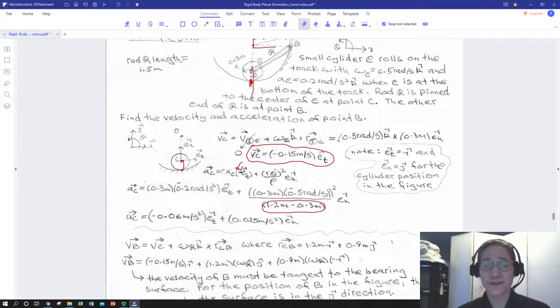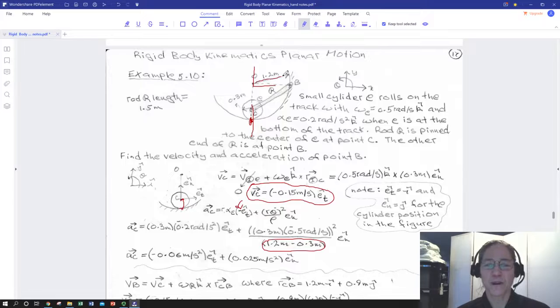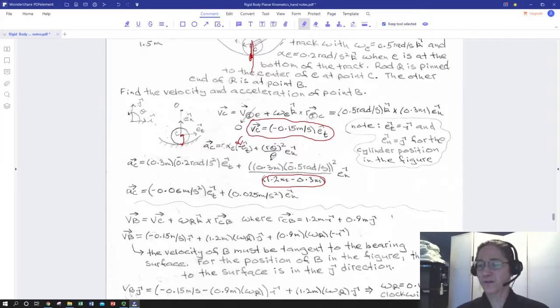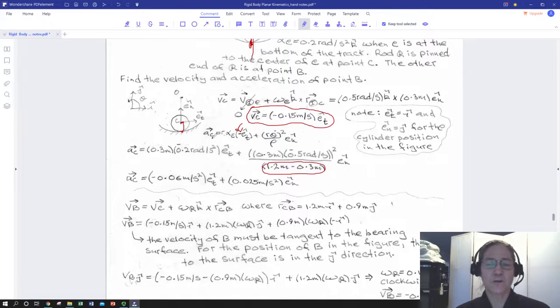Because we've got a curved surface, we've got a normal component, so we've got the radius of the small wheel, angular velocity, which we've already used up here, squared, divided by rho. And rho is of course the difference between the radius of curvature of the track, the surface we're rolling on, and the radius of our wheel. So that won't be rho of the surface, it's that difference. We can drop in values for this formula on the next line.